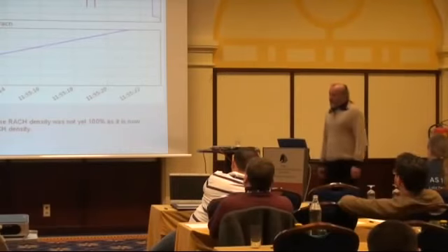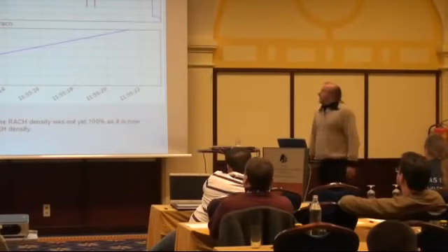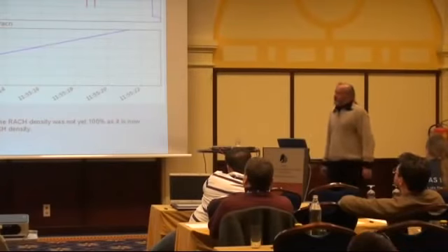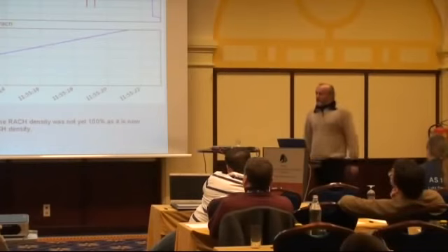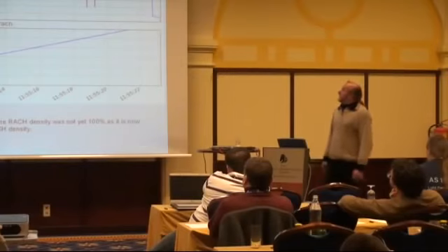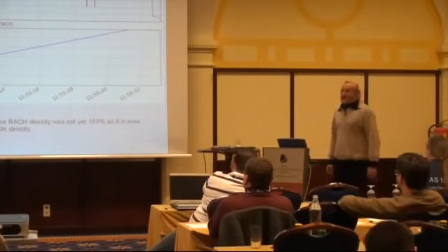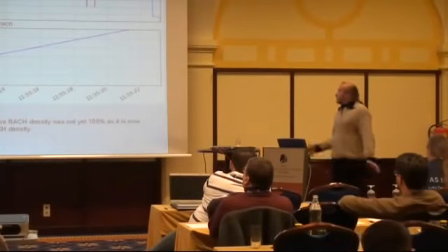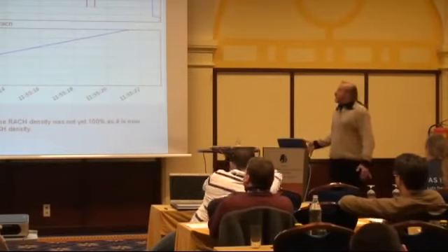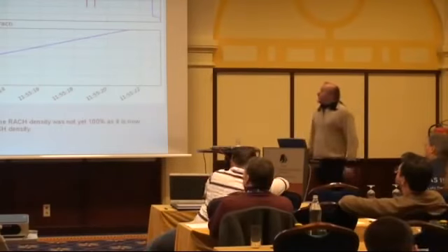From this diagram, we can see one thing. In the case of not jamming, another phone would only have a chance to get a channel in those places where the drops happen. If you look at the red lines, you can see that this gap is most certainly rather small compared to the length where all the channels are allocated. So if several phones try to get access in a large cell, they have the chance to get through, but only if they are exactly at that time where channels are already dropped.